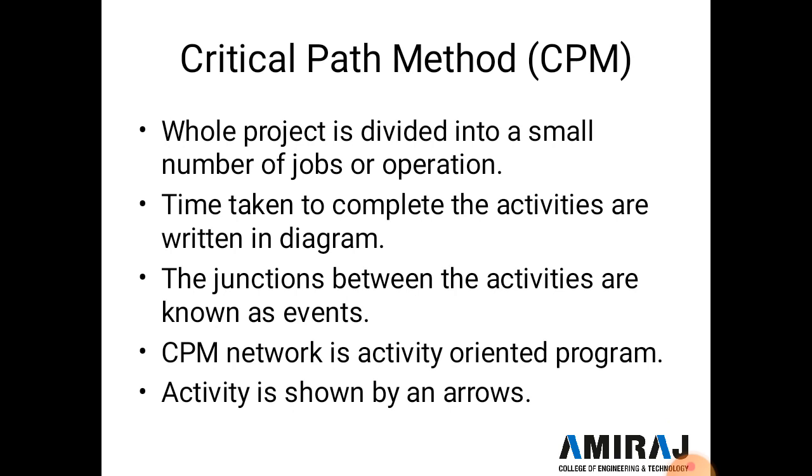So in CPM, the whole project is divided into a number of jobs or operations. What is the meaning of jobs or operations? If you prepare one bungalow, like a 2 BHK bungalow, the jobs are different: leveling, then excavation, then foundation PCC work, then brickwork in the foundation, soil filling work, then brickwork up to superstructure, concrete work at lintel level, then slab concrete work. So these are the different jobs or operations.